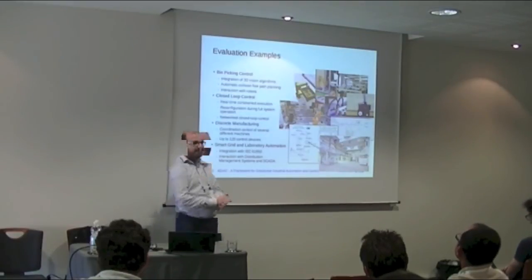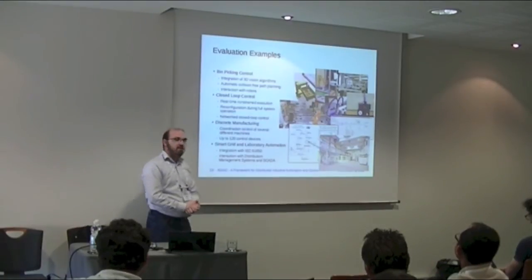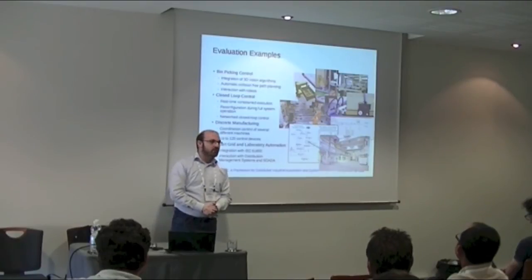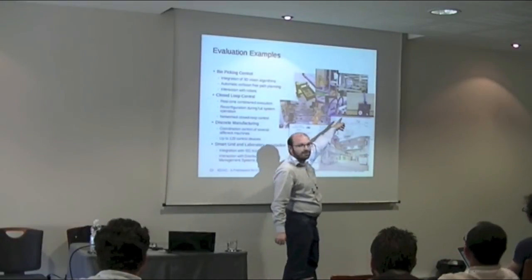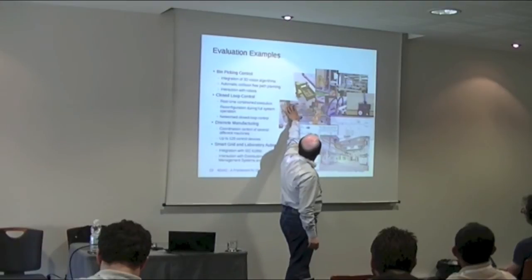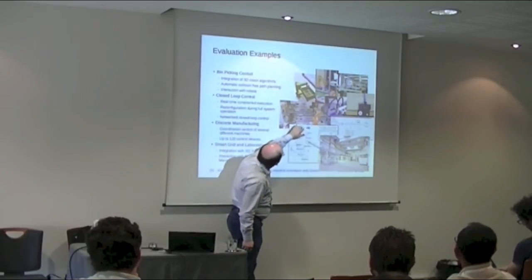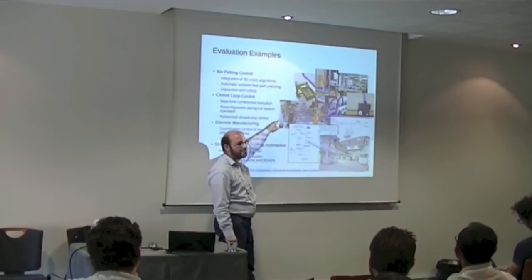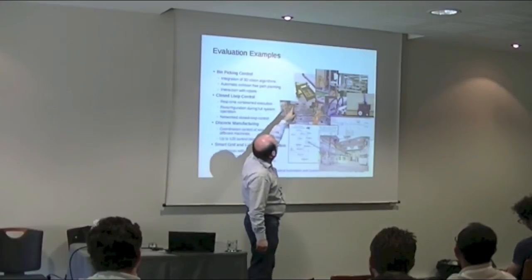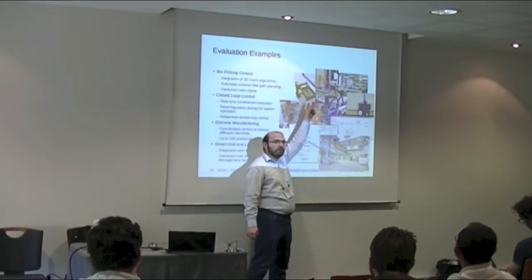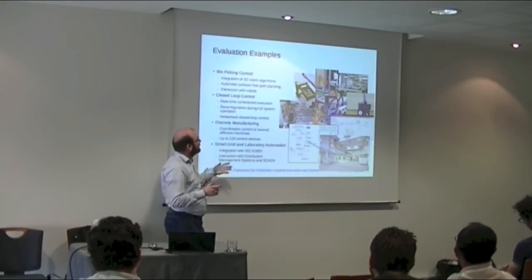Okay, and with this last slide, I want to give you a little impression of where we, the core team members, already tested and used 4DIAC. So you see things like inverted pendulum, the classical for teaching closed-loop control. Here some inter-process logistics system. It doesn't look so big, but it has about 120 control devices. So there we're really investigating highly distributed control. On top, this is one of our biggest applications with the most function blocks. There are about 1,000 or 2,000 function blocks in several hierarchy levels in one application.